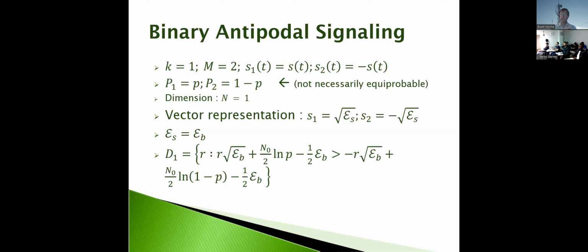So we can look at a particular type of signaling and say that we'll achieve a certain error rate if we have a certain amount of energy per bit versus our noise performance, right? And so the digital communications engineer can design the waveform and the signaling, and then the circuit and system designers can go and make that happen.